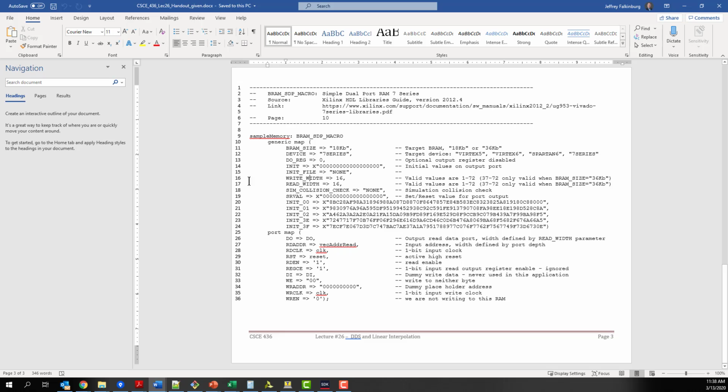Same VRAM as we had before, except I'm changing for Lab 4, we're going to change the width to be 16 bits versus 18 bits, because we're just going to add these values in. It's a lot more square because you can use 4 nibbles for each of the bits, or 2 bytes in the VRAM. You'll have to understand how we initialize these values. So it's going to go from initializer value from 0, 0. Before we didn't initialize it. We initialized our VRAM to 0. And now we're going to actually initialize it to a certain value.